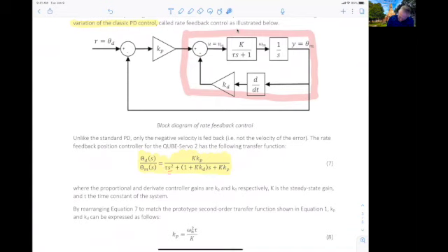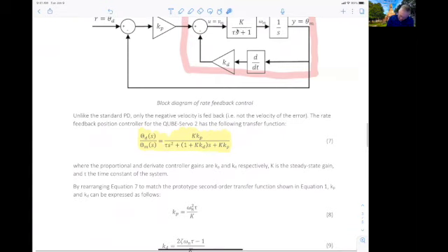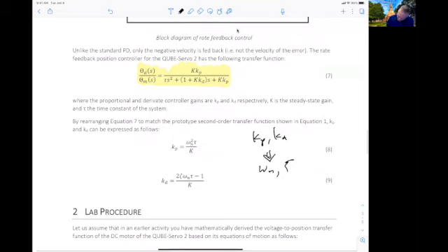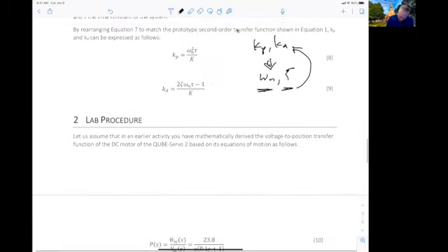We're saying this is the second order system, and from there we recognize the patterns. And so we're trying to relate Kp, Kd, omega n, and zeta. So on the controller design, we have Kp and Kd, and somehow those result in omega n and zeta. So the time shape of the response drives omega n and zeta, and then from there, that gives you back the gain constants that you need. So that's the point of this lab, to show how that works.